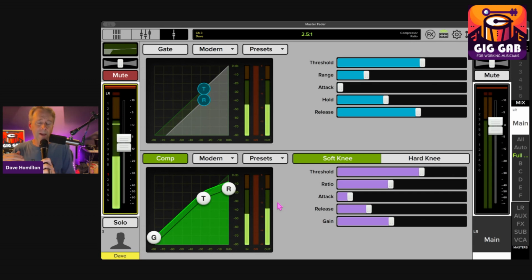General rule of thumb, the perceived volume level doubles every 3 dB that you go. So use that as your math. I like to have the compression sit things in about a 5 dB range, especially if I'm not out in front mixing. If we're doing what I like to call the braille mix, where you just set it up and forget it for the night, I like to have about 5 or 6 dB at most so that I know where the sound is going to be. And if somebody peaks in, it's going to be all right.